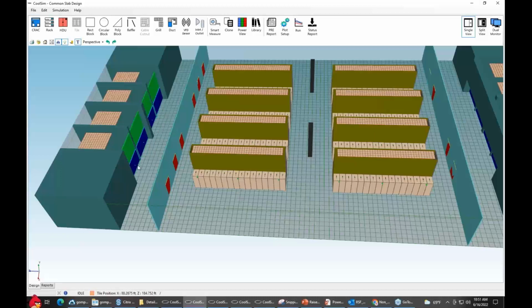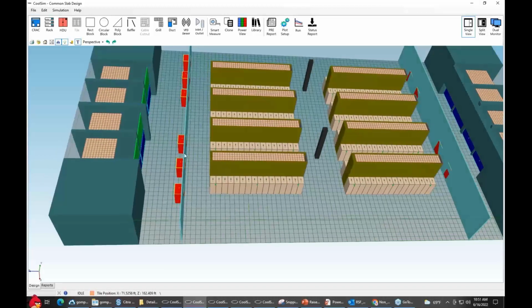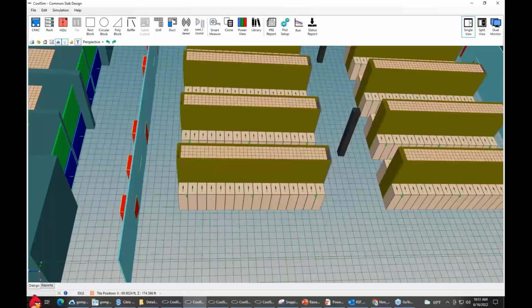These units are sitting far enough away. I mean, look at the distance that you have to put in place in order to keep the velocity from bothering these racks. And so this one is far enough away. This distance needs to be, generally speaking, well, it depends again. The problem with rules of thumb is it all depends. So I would say at least 8 feet or more.